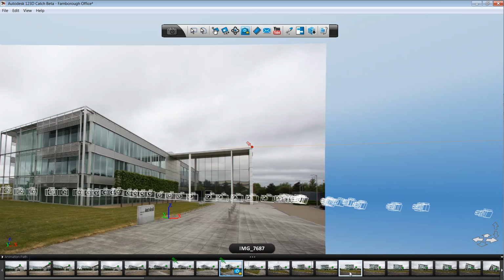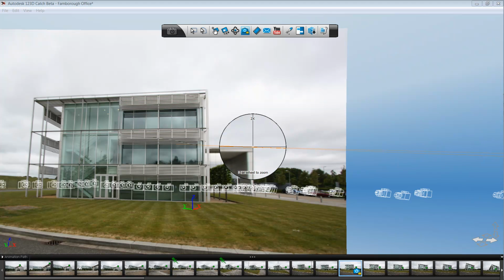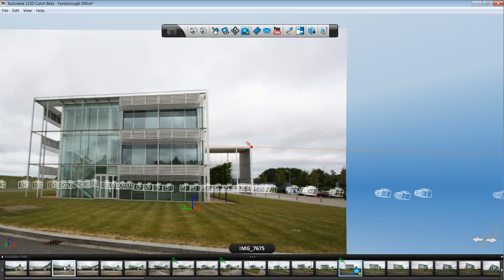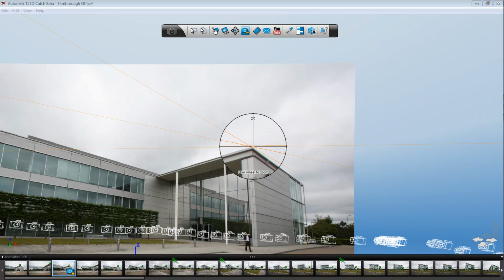So just step around and just start to add more reference points. It's also important that you look at really placing a point in a view that's oblique to the one that you created originally. Just helps with the software defining the three-dimensional space. It becomes very important when you're trying to really get an accurate tracing off of the building. So we've created some points there. We could do many more.